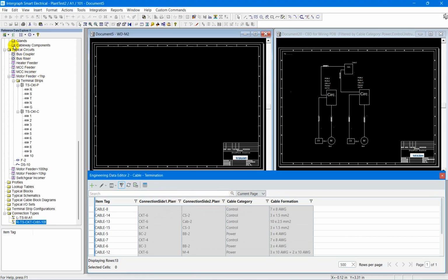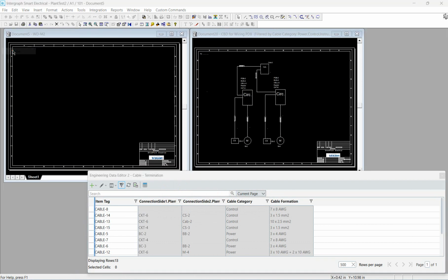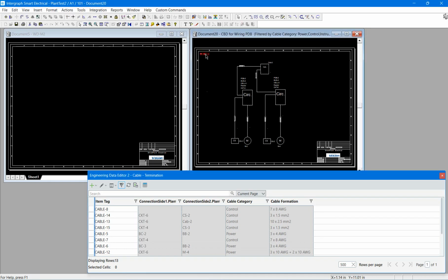At first, you create equipment terminal strips. The software allows you to manually create individual equipment strips, but I will apply a custom developed utility that will help to automate this work process. I will select all items in the block diagram and run the custom command.